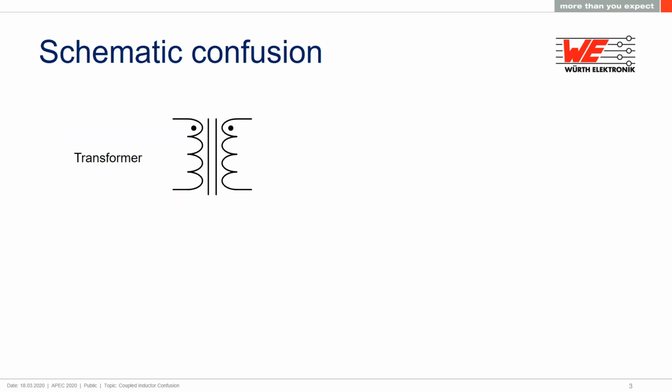In your typical schematic, we see this symbol used to represent a transformer. There are two wavy lines to represent the windings, and usually a couple of lines to represent the core. Polarity dots may or may not be present, depending on if polarity is important in the circuit. Use this symbol for common mode chokes, sometimes called current compensated chokes. It just looks like the transformer on its side, but it's not a transformer.